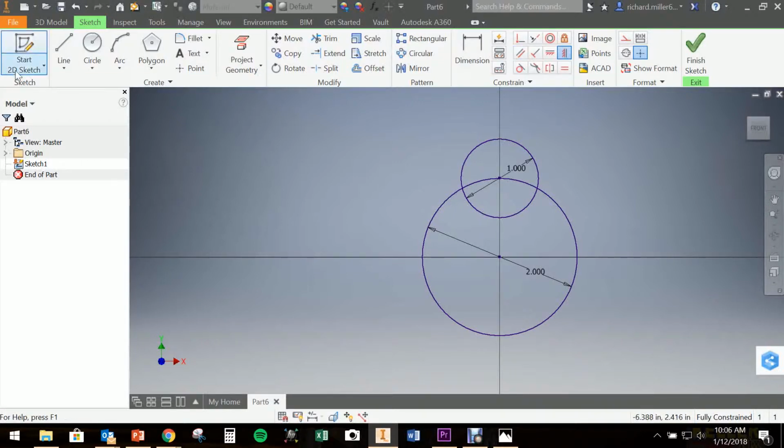So now all I need to do is go to the line tool, and I'm just going to create two lines. And these two lines don't even have to be touching my original spot. Now, the problem with the line tool that I sometimes find annoying is I can't just go over here and create a new one. It's going to put a line going from the last one contiguously. So I'm just going to hit escape, click the line tool again, and put my second line over here. And again, it doesn't even matter if it touches, and escape.